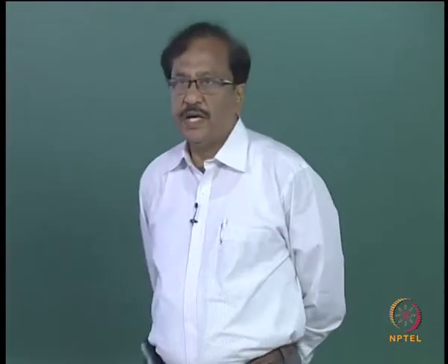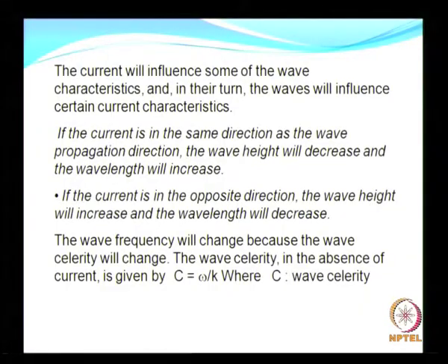If the current is in the opposite direction, what will happen? The wave height will increase and the wave length will decrease. The wave frequency will change because the wave celerity is going to change.